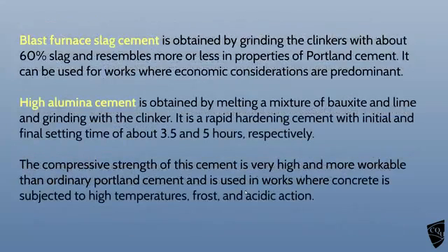Blast furnace slag cement. So, high alumina cement. Oh, that back in the 80s was bad news. It kept failing unexpectedly in swimming pool roofs back in the UK. So they don't use it anymore. It's a very fast setting cement, and it gets its strength very quickly. It's got a good compressive strength.